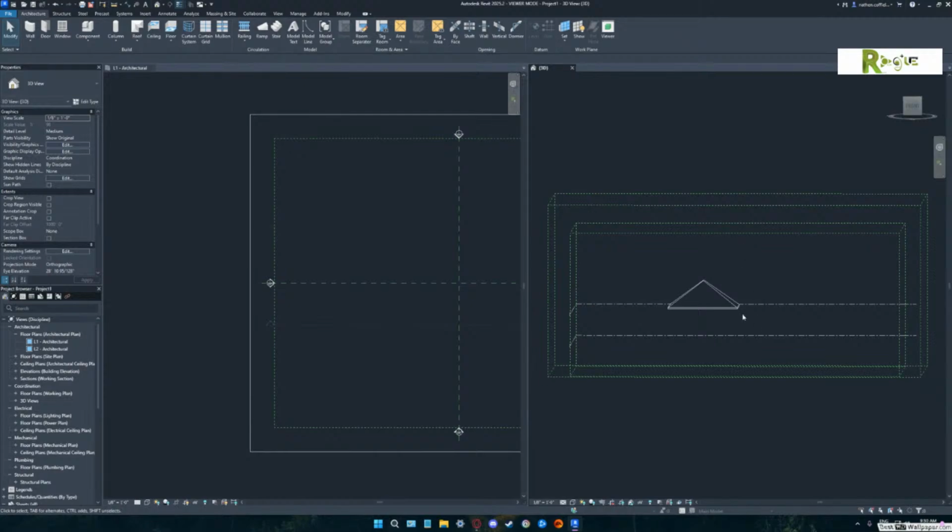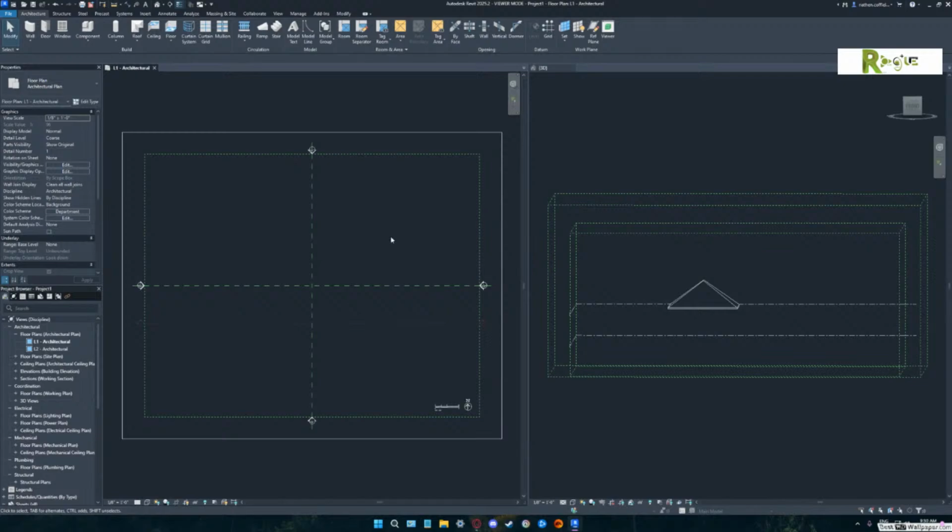See it? Do it in the other view as well. See what recenters. Zoom extents. It does a zoom to everything that's in the view. So if you want to go ahead and delete that roof, we're going to go through those commands that you played with. So if you just go to that 3D view and pick on the roof and delete that guy out of there so we don't have that shrapnel.